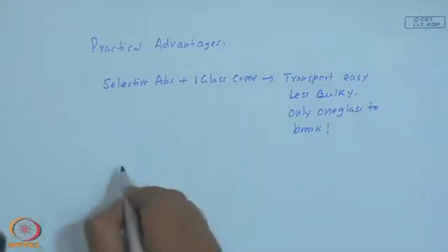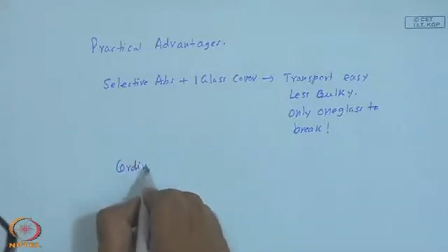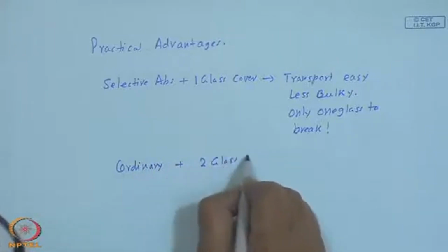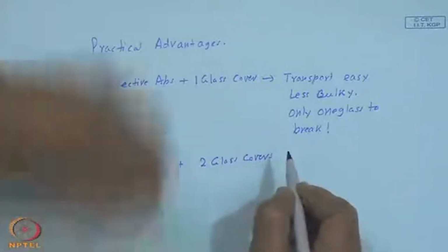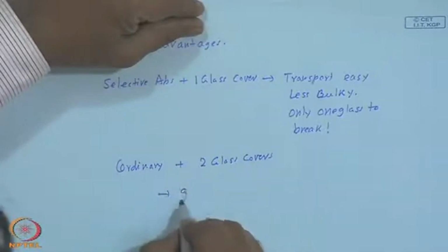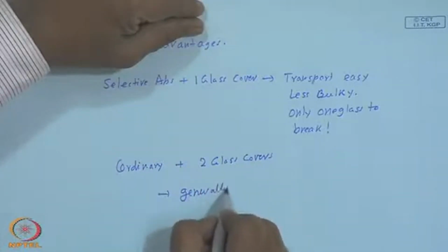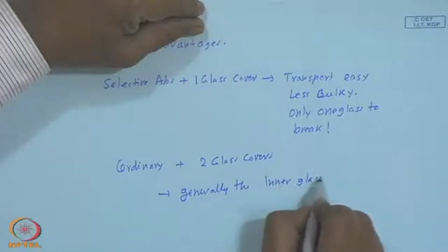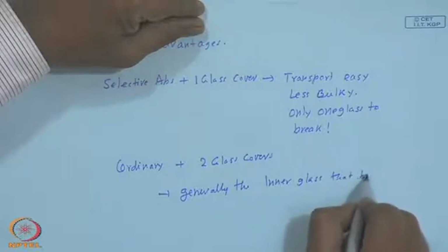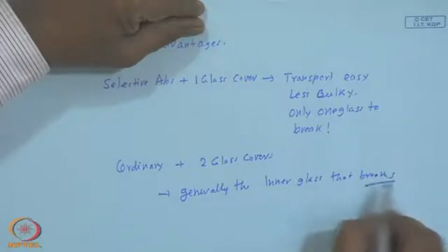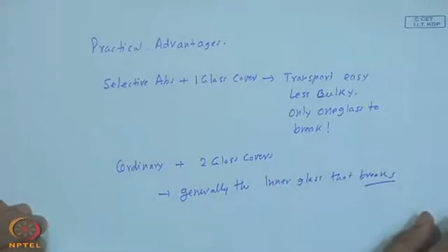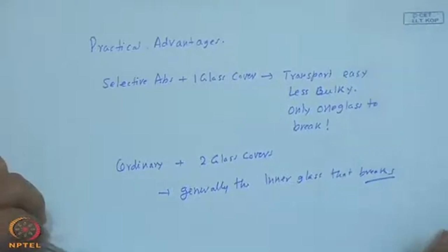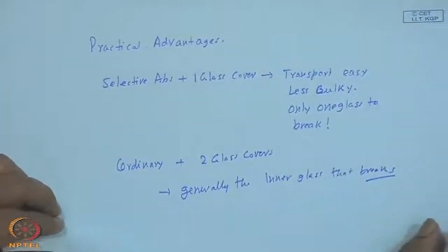If you have got ordinary plus 2 glass covers, it is generally the inner glass that breaks. In this instance, we do not mean that somebody has thrown a stone to break the glass, but essentially by thermal expansion and contraction.